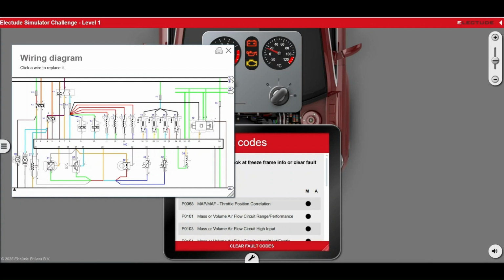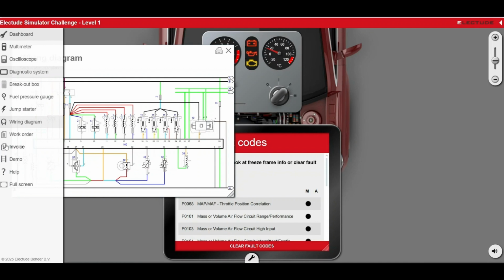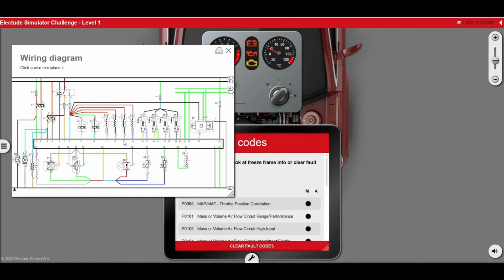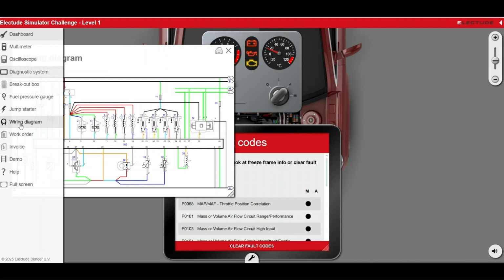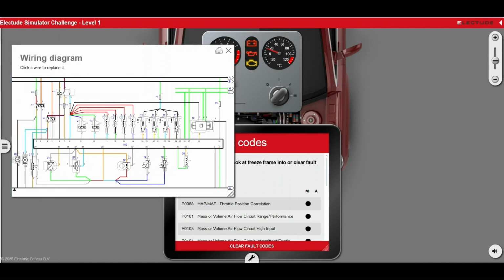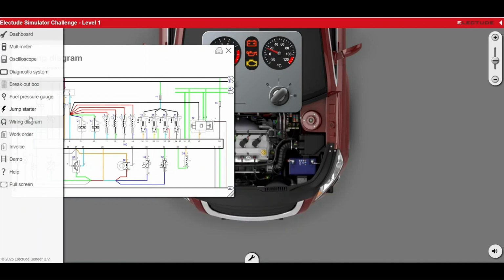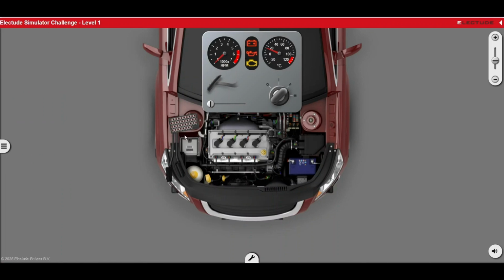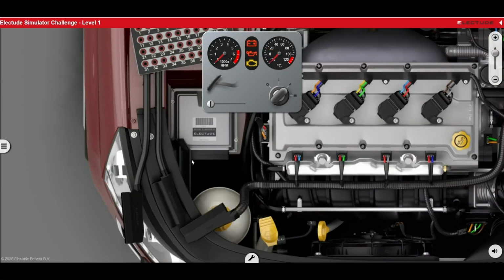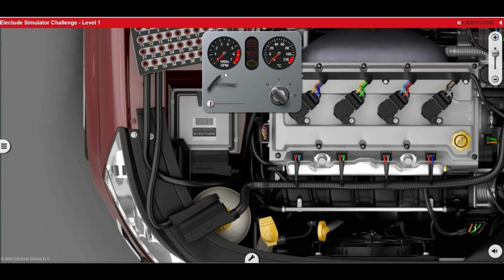So I begin to focus more on these sensors and develop a plan on how to test and verify what's missing. Clearly, all the listed sensors are either faulty or missing inputs. They're unlikely to be faulty, all of them. I mean, what are the chances that 4 or 5 sensors fail at the same time on the same vehicle?